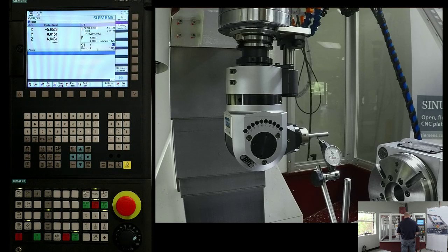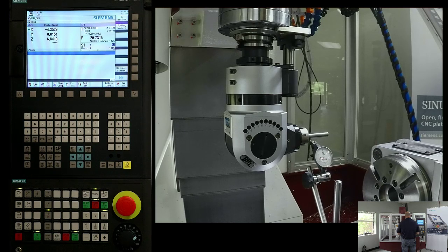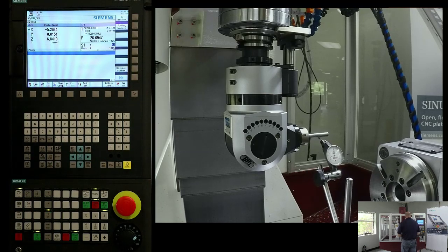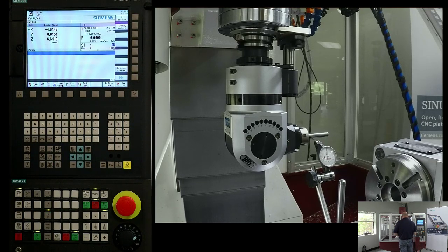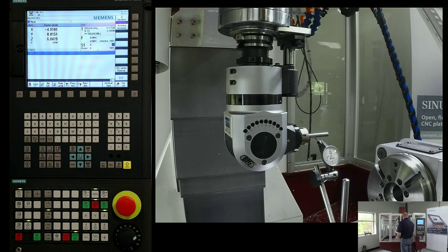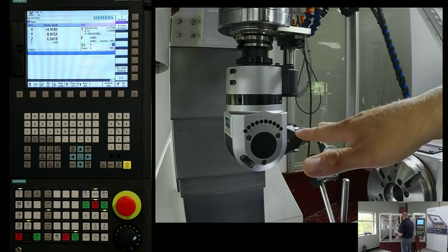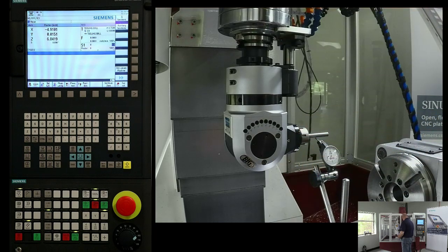And then, I'm just going to move down to a 0 mark, I would now move the X-axis back and forth and make sure this is straight. Now, it's important to know that this is physically straight on the machine. If it's not, I could have another mechanical issue. It's probably not necessarily something I would want to compensate for in the head. So if this whole column was tipped up and not running parallel to my table, that could be an issue.